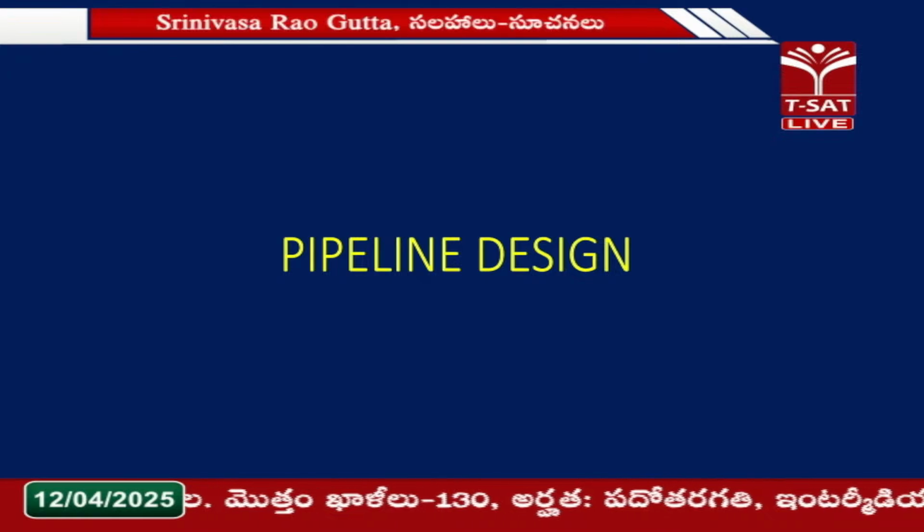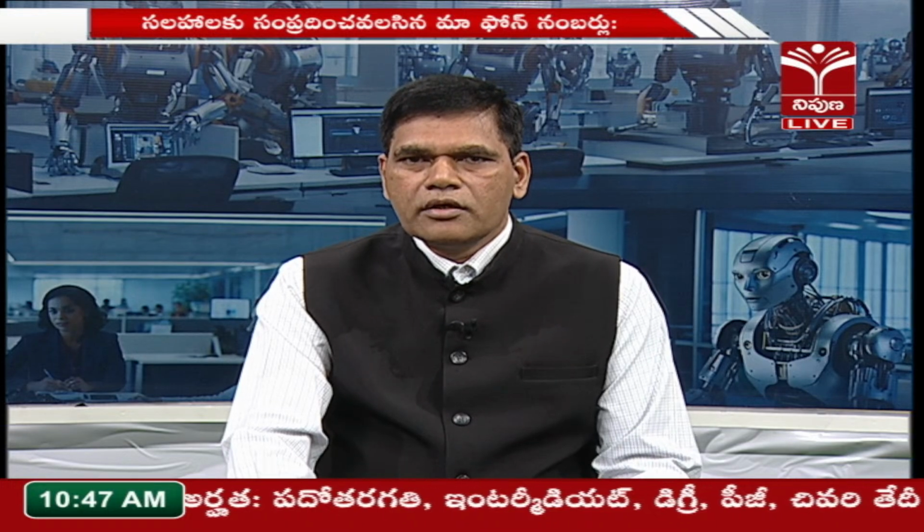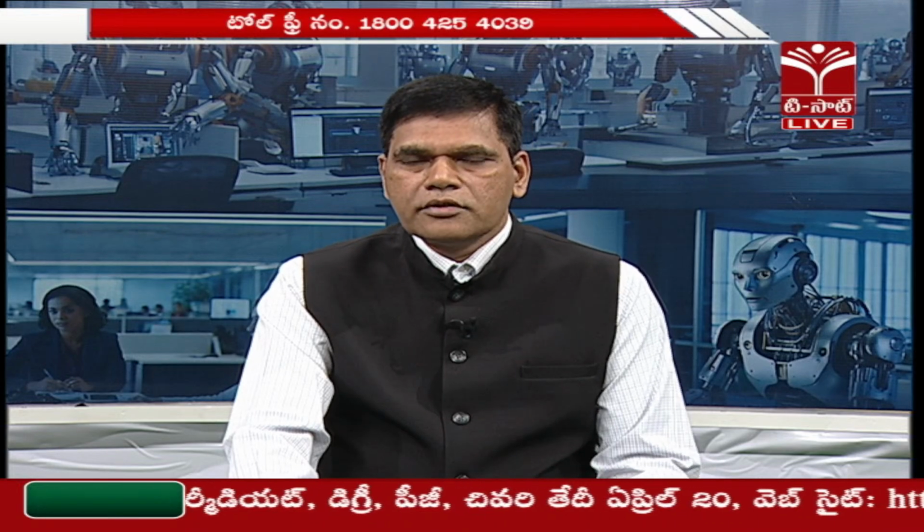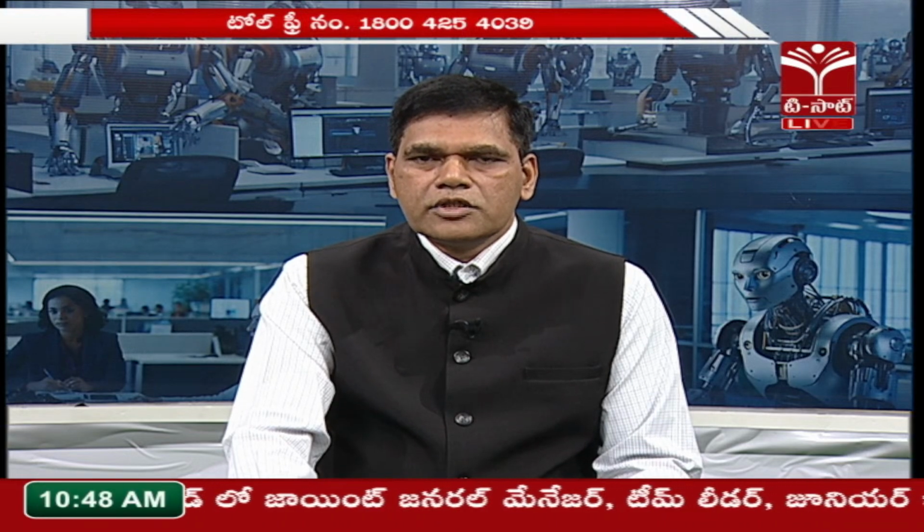The next topic is about the pipeline design. You have a CPU that is operating every clock cycle on a specific task, and when you go through that task, how can you enable the next task before completion of the first task? A task in this case is an instruction decoding and executing, that we talked about. So, before you could complete that particular fetch, decode, and execute cycle, how can you sequence the next instruction into the data path? And this is more like an assembly line.